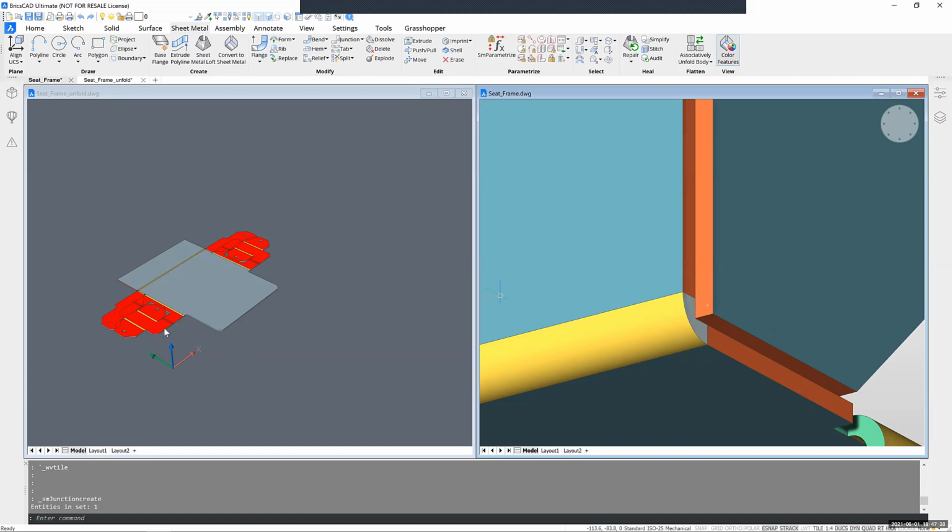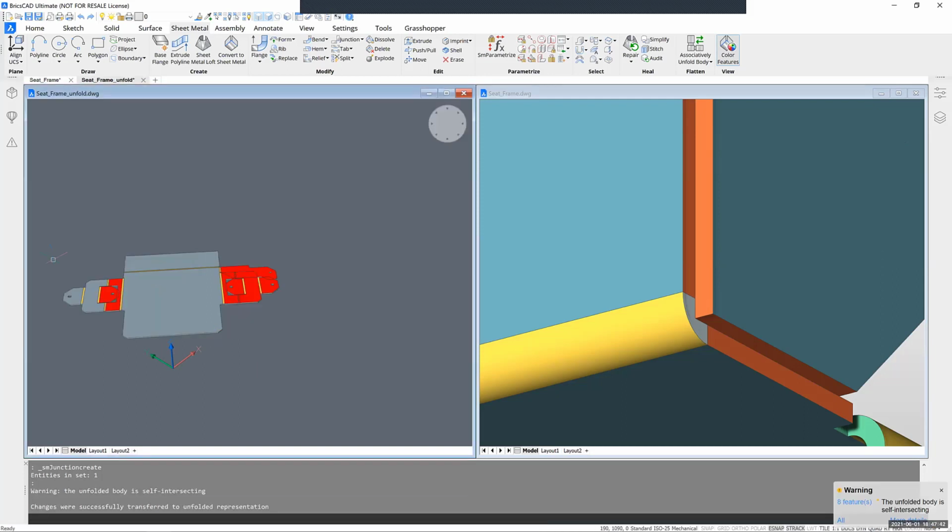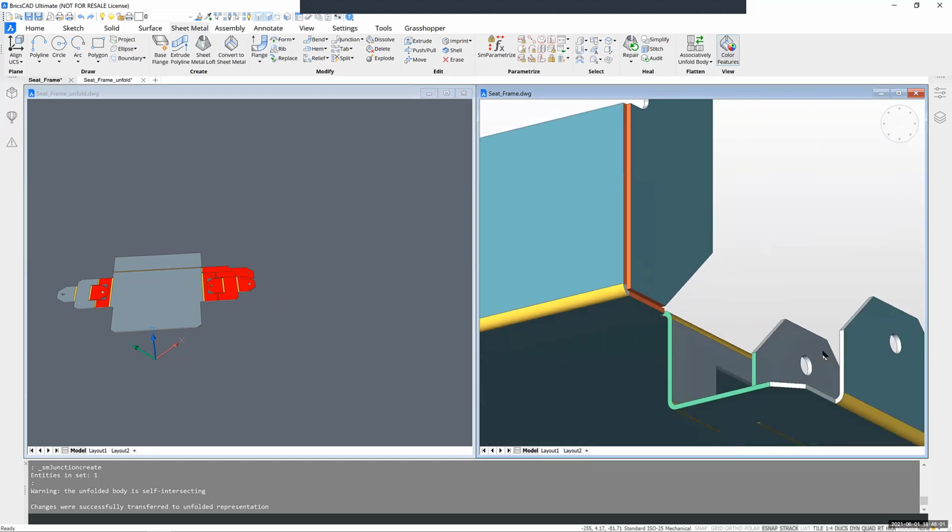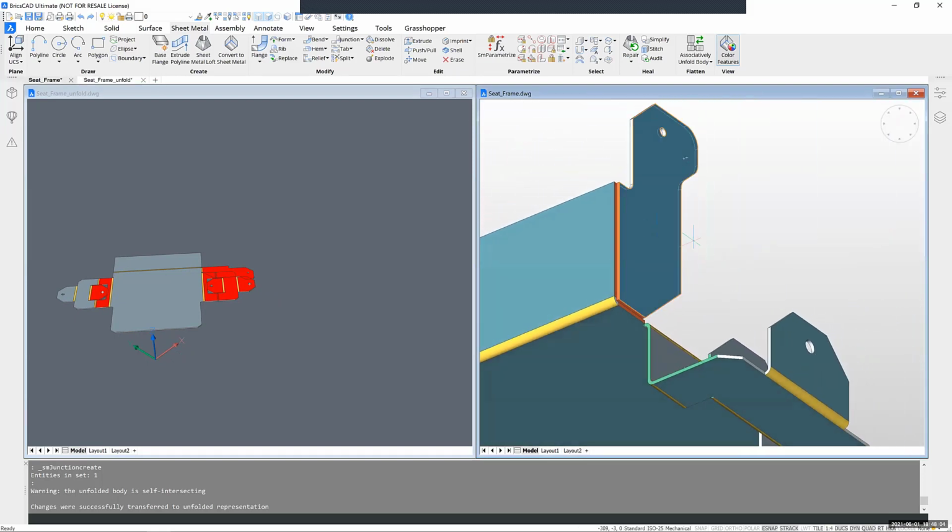And then if I now pay attention, once I click in the other view, it will update itself, and you should see less red in this area. So now it's updating itself, and you see less red. Apparently the view tilted so that you can easily see here is now unfoldable, as opposed to before. But what we actually did now, if I go back to the 3D view, is that we made this part entirely loose. It isn't connected anymore.